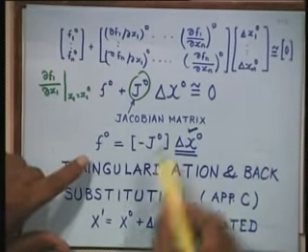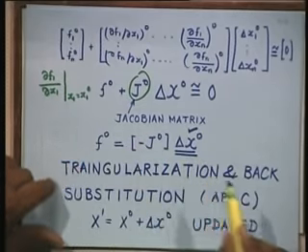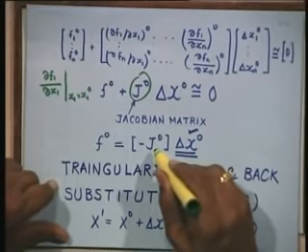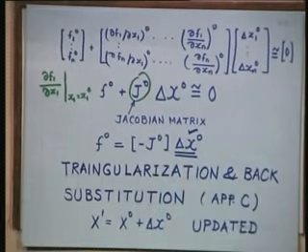So now I can write further f0 is equal to minus J0 delta x0, and this delta x0 we have to find out. So it needs an inversion of the Jacobian matrix. This is another negative point of this method. In Gauss-Seidel we didn't have to use any inversion. It was straightforward, the easiest method to understand. Even an ordinary person can solve using Gauss-Seidel. That's just one equation, as we have seen. Here you have got to invert this matrix in order to get the corrections.